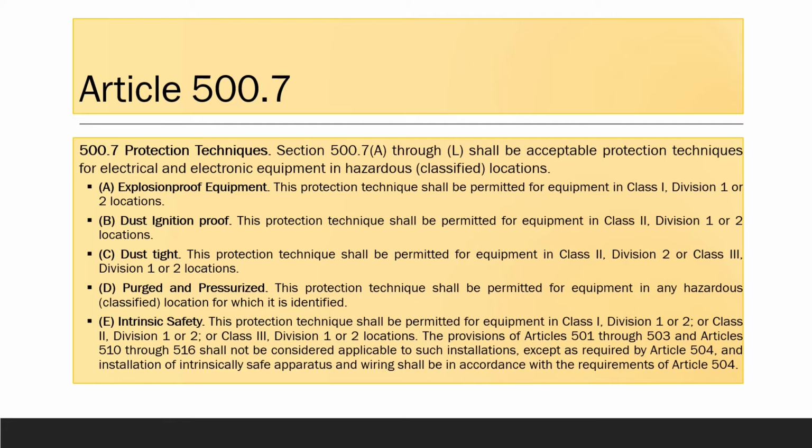To put it simply, before an area can be pressurized, it must be purged of the current air. Pressure must be maintained at a level of at least 25 Pascal or 0.1 inches of water, with all openings closed, and must provide a minimum of 0.305 meters per second or 60 feet per minute through all openings capable of being opened.